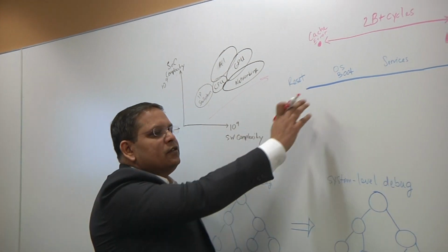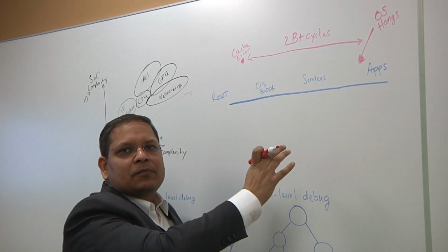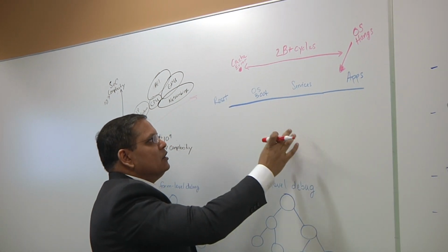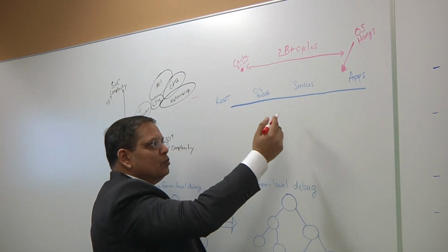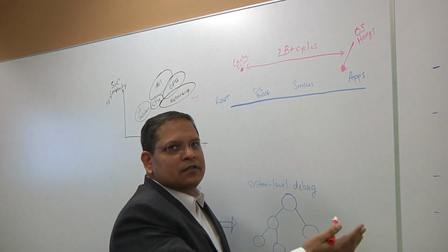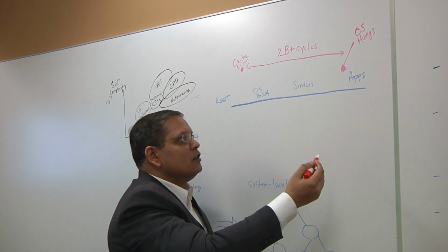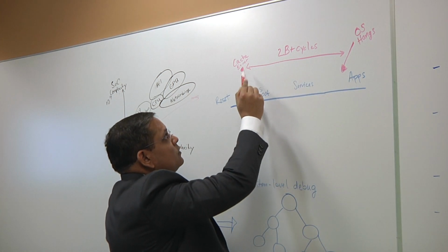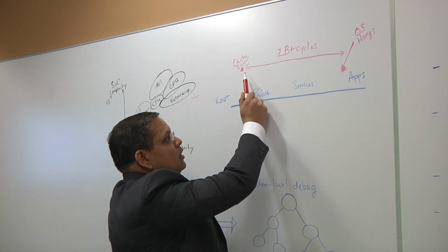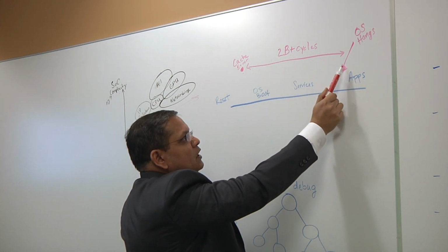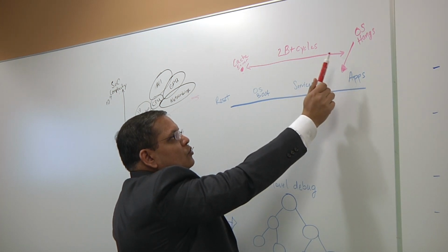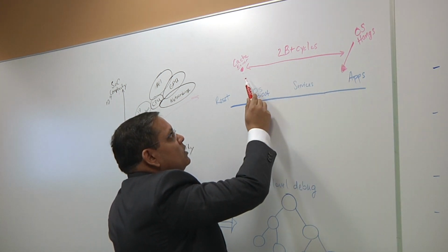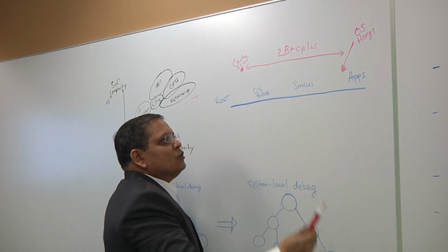Okay, so actually here is a picture of a very common example that we see with multiple customers. And here I have a case of an application running in emulation. So design goes through reset, we do OS boot, we set it up for some application, and let's say that in this case I've done the Windows boot and I'm running Internet Explorer. And while doing something in Explorer, my OS hangs. Now the problem could be because of a cache error that happened during the boot itself. And from the error to the first sign of failure, you've gone through billions of cycles. So now debug has become challenging in the sense that you have to traverse back so many billions of cycles to find the root cause. And this is what we need to solve.